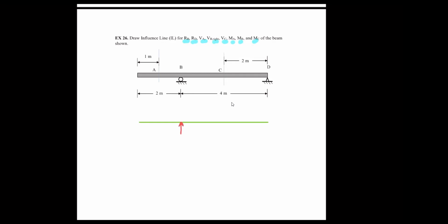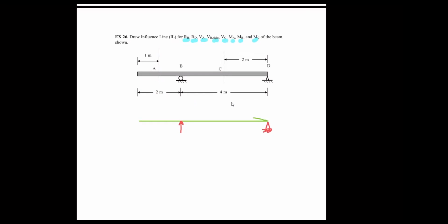Okay. Remember, I still have this. So when RB moves freely, you just go like this, right? Because we have a hinge, so it will go up like that. The dotted line will not come straight. That's because RB is now free to go without restraints. It moves up freely, so I can just now draw a straight line. Okay, so the shape of the influence line becomes this one.